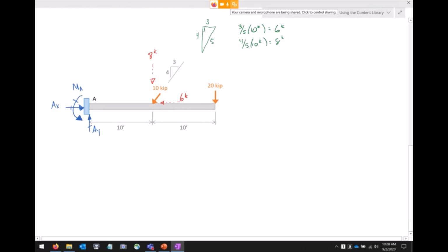Okay, so we've got these 3 reactions we've got to solve for, and one of the things I had mentioned is that it actually doesn't matter what order you solve them in. You can solve for the X direction, the Y direction, the moment reaction, in any order, because all of them coincide at the same point. There's no real strategy. You could just start going through the equations one at a time. So that's what I'm going to do.